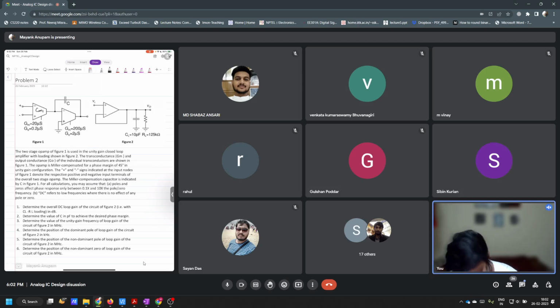So you see, this is an approximation. We have understood it in this way, right? That P1 is appearing because this capacitor is being multiplied by this, right? And you say that P1 appears here and then it falls at 20 dB per decade and then P2 is at a very high frequency. But this is a very right question, that this P1 approximation holds only for low frequencies, right? But at very high frequencies, this curve should not be like that, right?